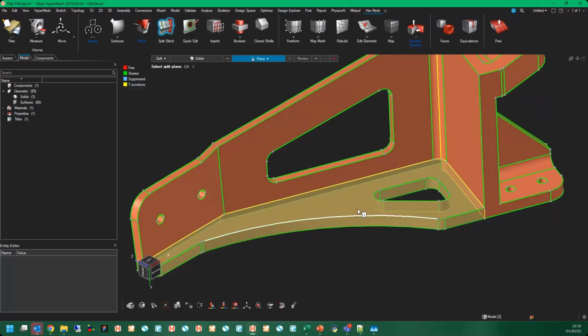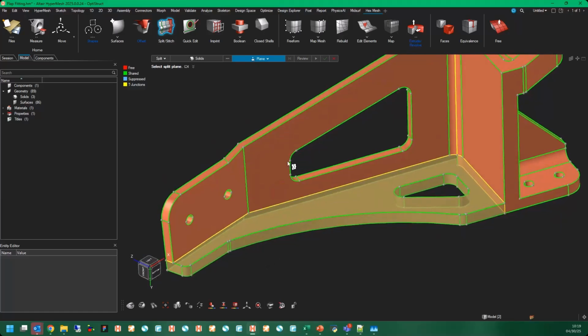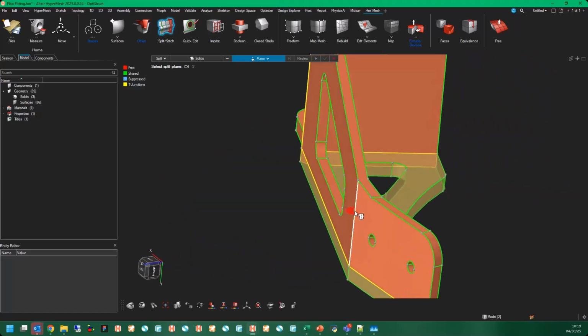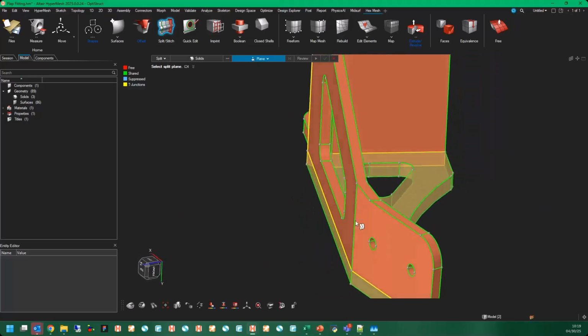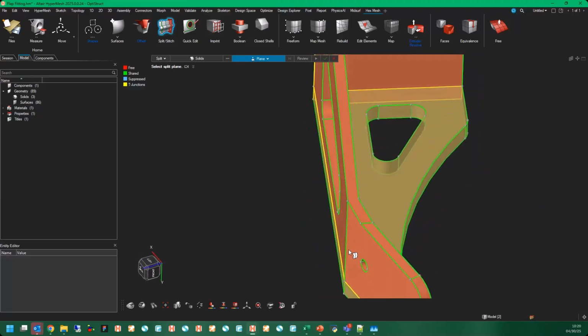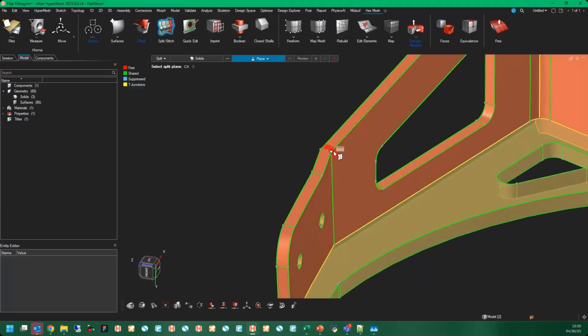You put a mesh on either of the top or bottom faces here and extrude it through in the other direction. This one is going around this corner here, and so there are a couple of ways we could attack this. We could just suppress this edge, but we probably don't want to suppress it because it's somewhat of an inflection point in the part, and we still want to capture that. So we'll just split it.